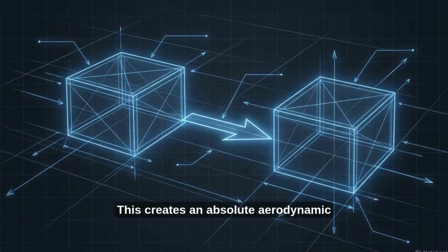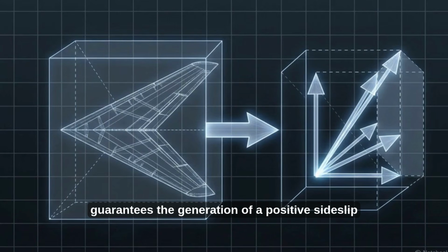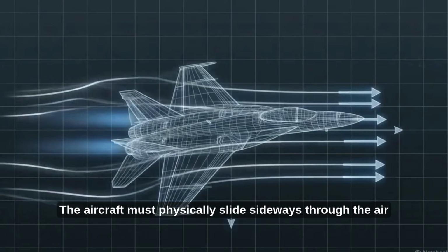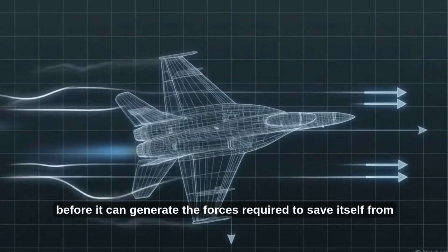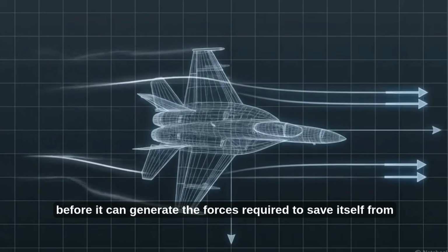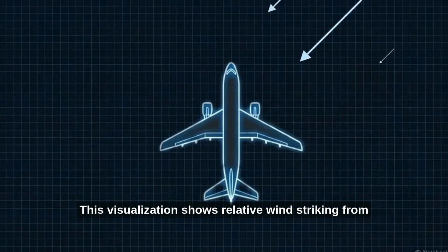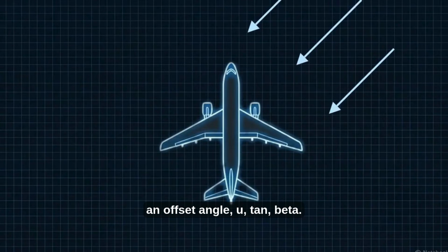This creates an absolute aerodynamic rule. A positive angle of roll mathematically guarantees the generation of a positive sideslip angle. Roll stability is entirely a byproduct of directional dynamics. The aircraft must physically slide sideways through the air before it can generate the forces required to save itself from rolling. This visualization shows relative wind striking from an offset angle, U tan beta.